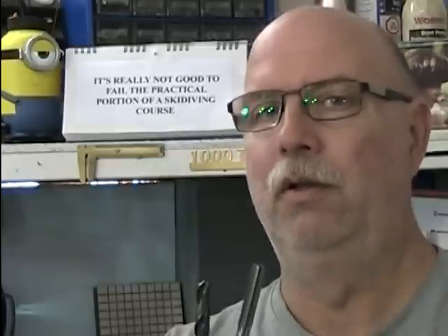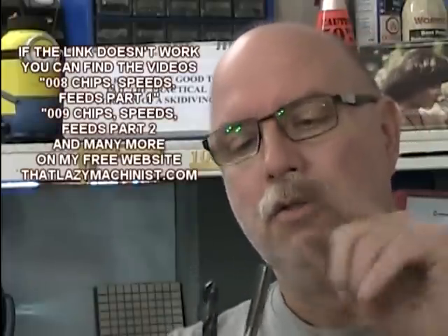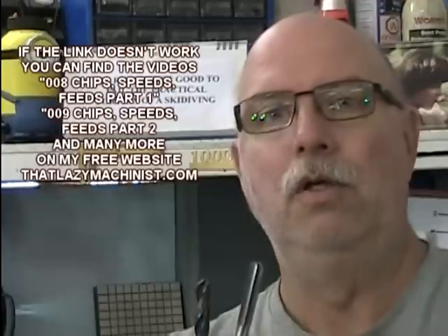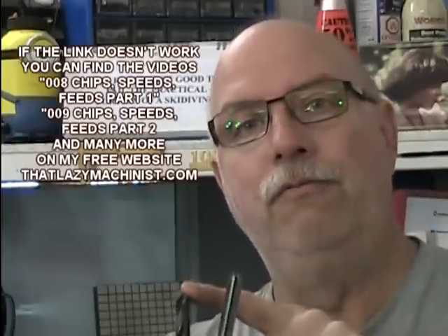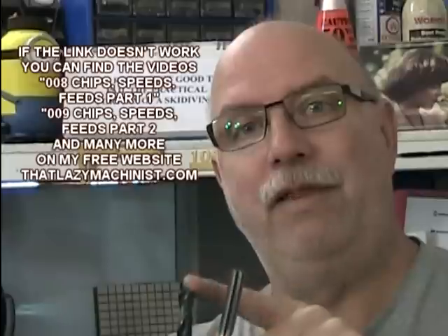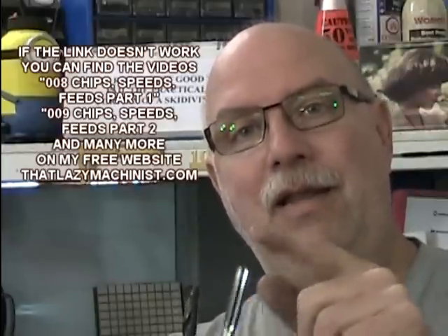This reamer has 6 cutting lips, and larger reamers could have up to 8. Well, obviously, if I want to maintain the same chip load, and I do. What is a chip load? It's the thickness of chip per tooth. So this drill bit was picking up a chip load of about 1.5 thousandths of an inch. I would like to maintain that chip load.